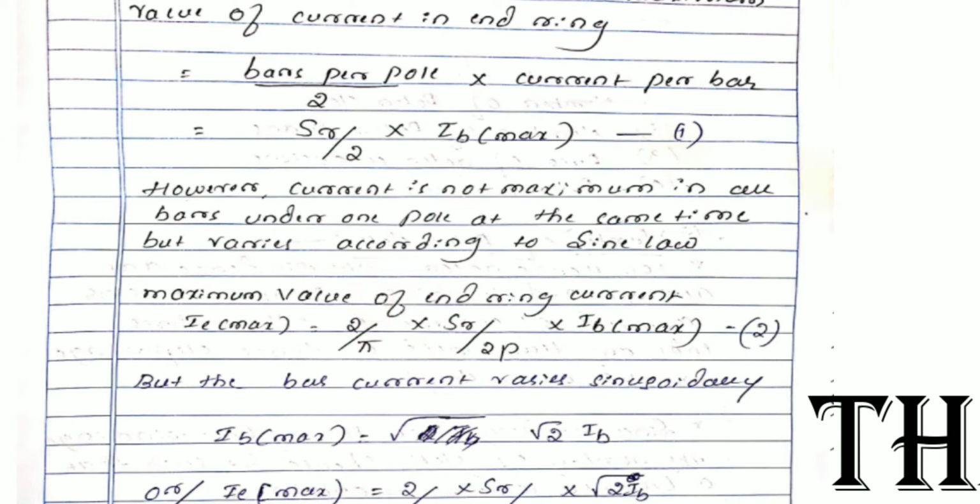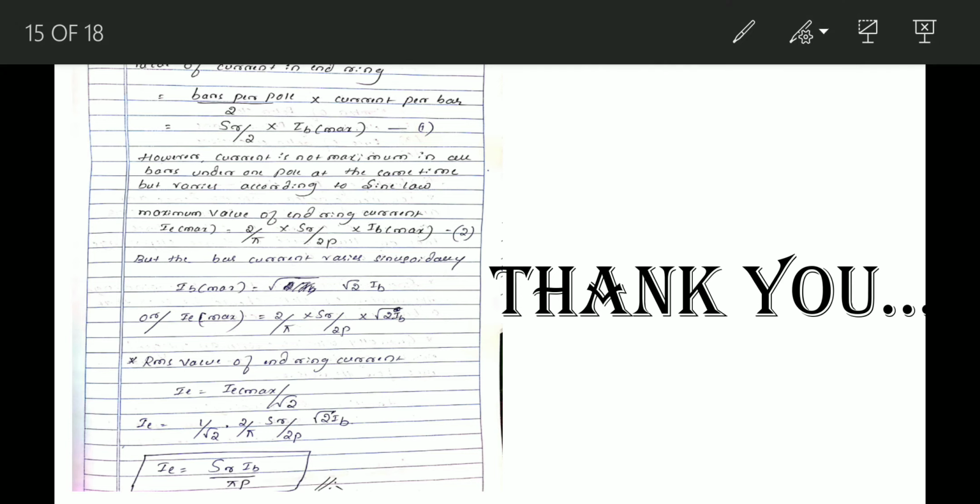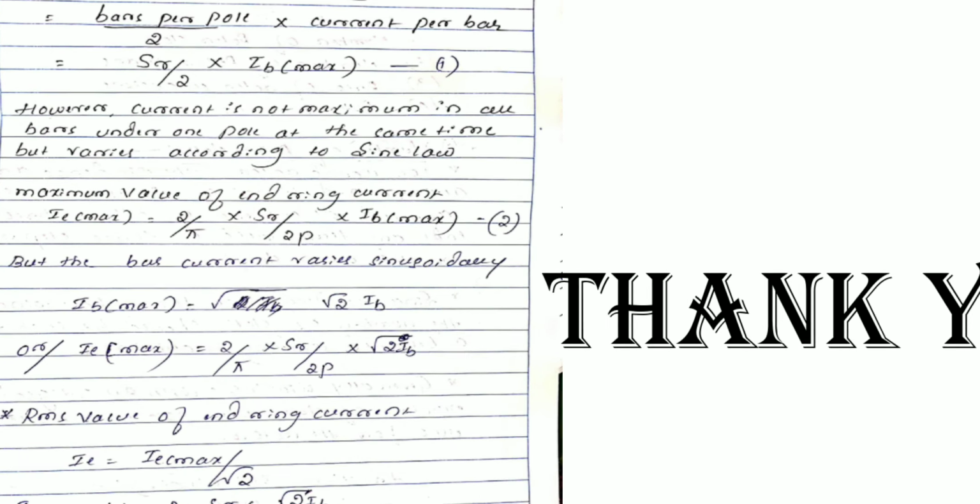In a particular bar, the current will be varying in nature. That is the reason, for the sum of all the currents, whether maximum or minimum, at the same time the current will not be maximum in the rotor bars. That is why I took the average value, 2 divided by pi. Into this is the current which is flowing in the end ring from the first equation, which is written as SR divided by 2P into IB max. Call this equation 2.